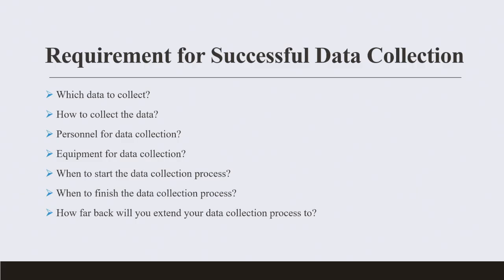Now, when to start, and this is also another important question. One thing I learned when I started doing business with LiDARs carried on drones: you better pick a clear day. You better pick a day with the least amount of wind, because that ends up with more accurate measures. Think about talking about light speed, 300,000 kilometers per second. So any deflections or any misalignment in your devices, of course AI can self-correct, but why would I make the error and try to correct it to begin with, right?